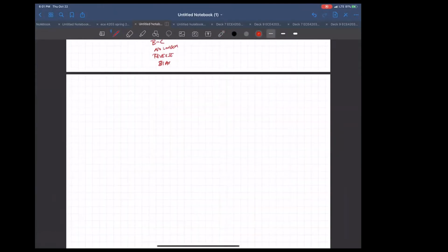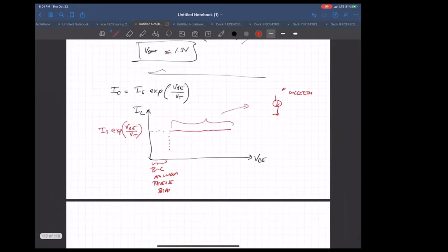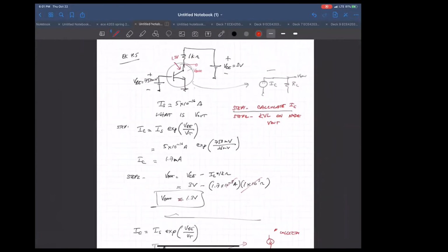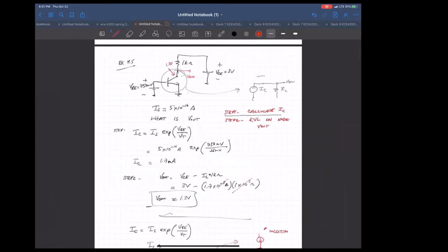Okay, can I ask you a question? Sure. On the previous question, sorry to go back to it, you said V out is 1.3 volts. So is that reverse or forward bias? So look at this. This point here, this V out, is at 1.3 volts. And this VB, the base emitter voltage, therefore the base is 750 millivolts.